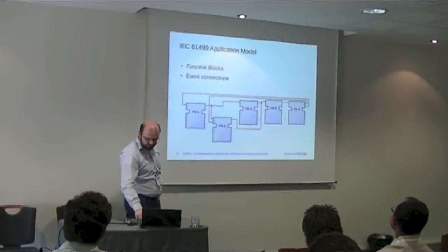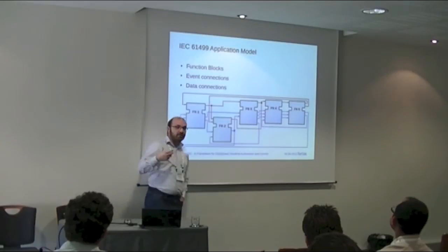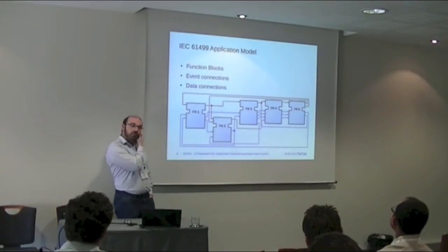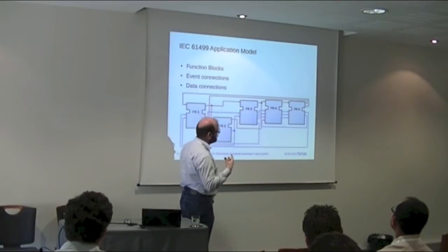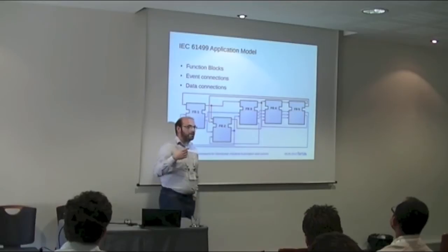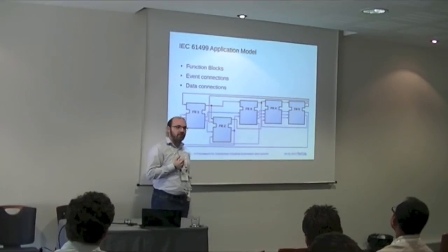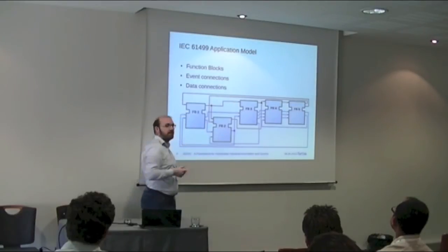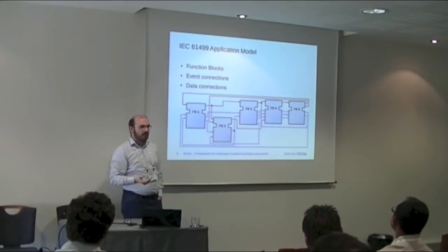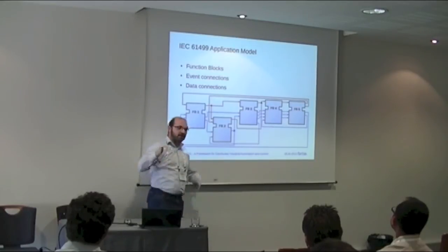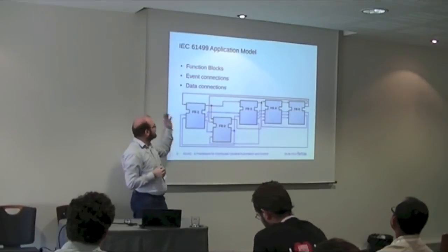Connected with event connections, connected with data connections, and here you are. Function blocks and our applications, which is very important, are developed independent from the system configuration, which hard control devices are really available. So you can here really develop your logical function. You can say, I want to control a piston that will press a knob into a door or whatever. And this is my functionality.